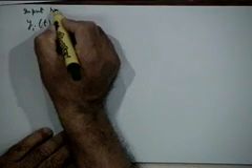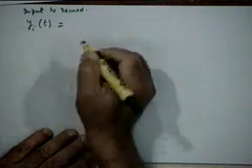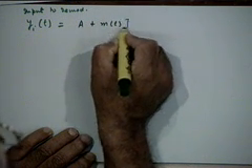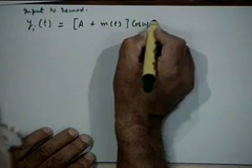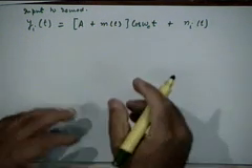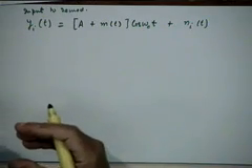So, the input to the demodulator is y sub i of t, which is (A plus m(t)) cosine omega c t, plus the narrowband noise that is coming along. Remember, when I say input of the demodulator, we are considering the output of the band pass filter, which is the front end, the first stage of the receiver. The receiver will always be associated with a band pass filter to pick up your desired signal. It will have a bandwidth of B or 2B. In this case, it will have a bandwidth of 2B.